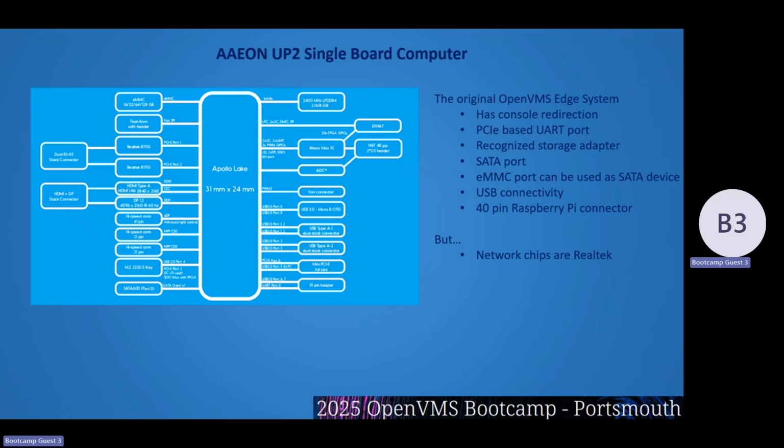Another option for this is they have these little adapters that instead of ending in the DB9 connector, they actually end in a USB connector, and it's got a USB to serial adapter on the chip. So you connect your laptop to that, fire up your favorite terminal emulator, and as long as it has whatever drivers it needs for what's on the end of the USB, like FTDI, for example, you hit return and you're looking at a username prompt.